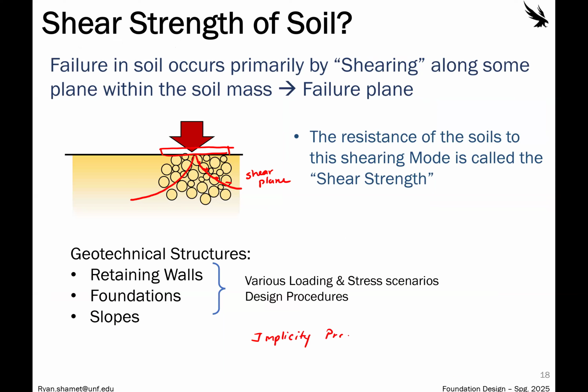So it's a little tricky compared to steel design or structural design, where you have a general understanding of the mechanics of steel, like the yielding stress and the compressive strength and the tensile strength. And then you apply those properties to steel in the design. For geotech, we kind of bypass that. We know shear strength as a concept, and instead we develop capacity functions, or the strength against failure for these certain cases, because the failure case is going to be different for each.